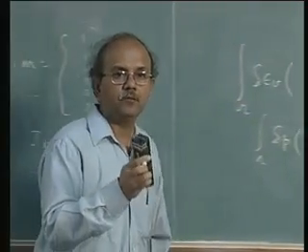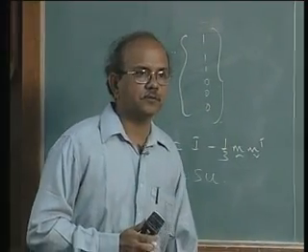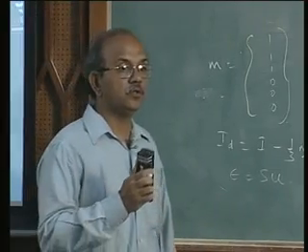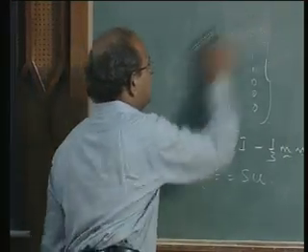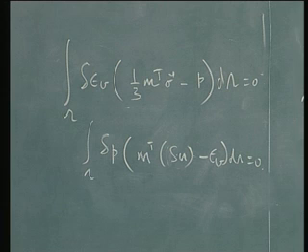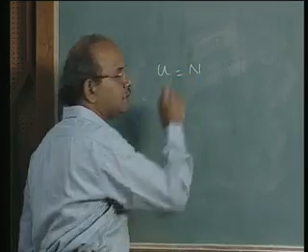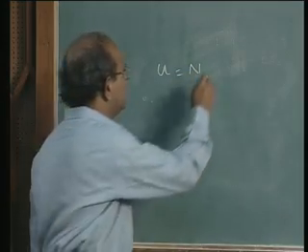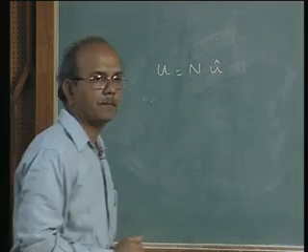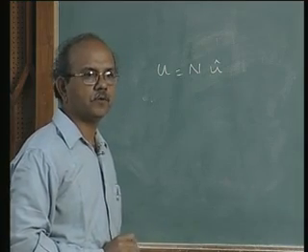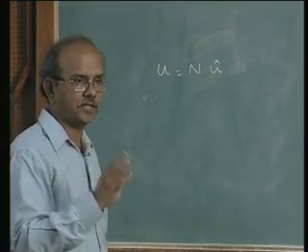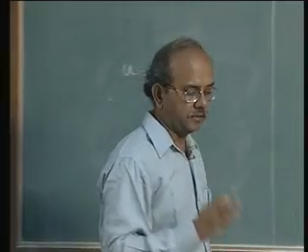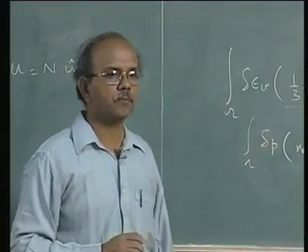Now, what's the next step? What am I going to do? I'm going to do exactly what I did for u, for p, as well as for epsilon v. In other words, I'm going to write u equal to my good old friend, the shape function, into, say, u hat. What is u hat? Remember, yesterday we said that they are the displacements of the nodes.